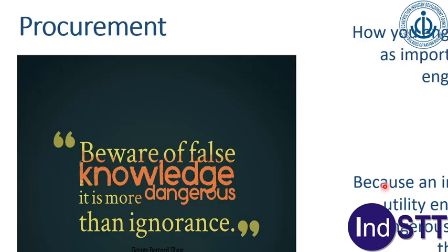So a multidisciplinary approach: the team should be a mix of geophysicists, surveyors, CAD engineers, etc. This is basically the combination of SUE engineer, CAD engineer, utility engineer, geophysicist, survey engineer. So this is a stamp which I will talk about later, but this actually is the person who can be called an SUE engineer. The Indian standards deal with what an SUE engineer is. It deals with survey grades, level links to MSL, coordinate system, use of multiple technologies, clear identification of quality levels, experience, manpower, equipment, etc.